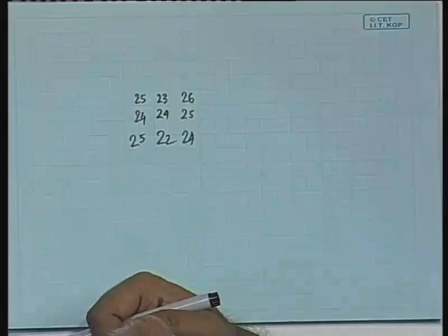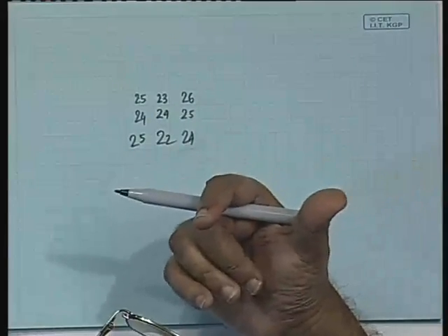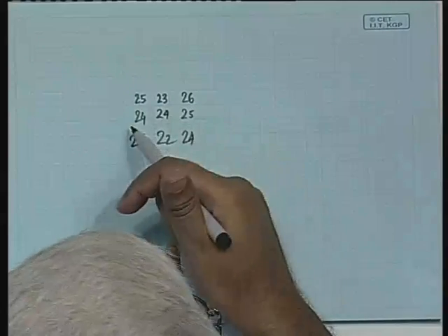And then we can also decide to give some kind of incremental representation: over and above this DC value, the individual pixels are going to have some variability pattern, where the variability could be just the numbers which are the differences with the immediate past values. Which obviously leads to a differential encoding. So, here if we are sending the first pixel, let us say the first pixel is 25, and then the next pixel we send as 23, next as 26, next as 24.